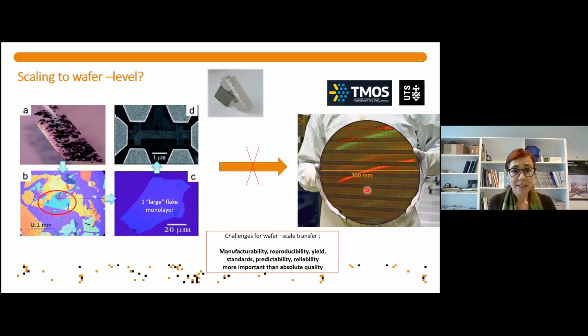And this means that even though you might be able, and this has been demonstrated, by the way, I believe by IBM, to synthesize a big flake of graphene and transfer it completely to cover the whole wafer, it does not mean yet that you will be able to integrate that. There's a lot of problems that can still come out. That's wrinkling, delamination.